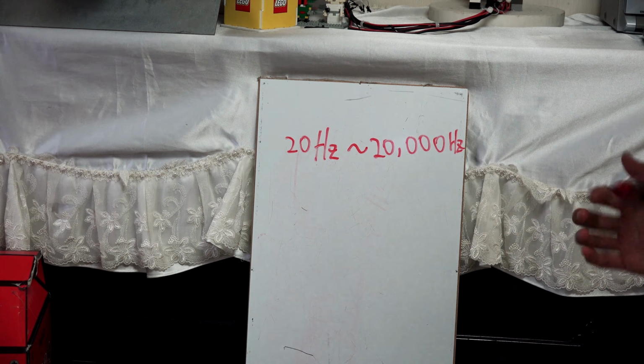Triggering is really easy. Just digital write high, delay for 10 microseconds, and then digital write low, and that's all.